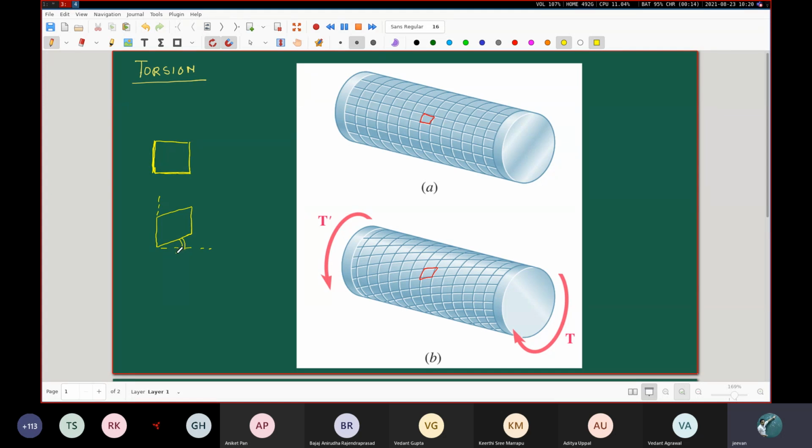Now when you have shear strain, what does that lead to? Do you not also have, through Hooke's law or any other material behavior, the generation of stresses? Take your mind back to the stress strain relationships which you studied in your first year, the generalized Hooke's law. Please note that for the purpose of this course, we will always be referring to linear elastic isotropic materials, as we had discussed in our very first class.